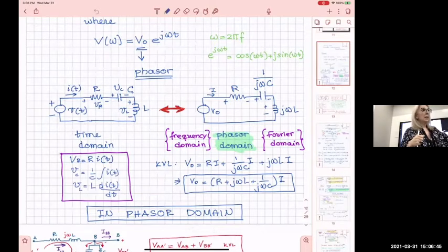They behave a little differently, but the fundamental thing is that the way the fields are excited and create a voltage and a current, which is what we use in circuits, those voltages and currents go exactly the same way on these lines as they go in microstrip. Maybe the fields do not distribute exactly the same way, but in terms of the voltage applied across the conductors, between the top conductor and the ground, and the current that flows along the length of the conductors, they behave the same.